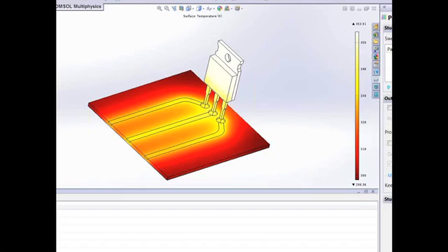Now remember that there were some dimensions that I linked to COMSOL, and the first one was called D1 at sketch 2. So this was a dimension at sketch 2, and there was a COMSOL parameter set up so that it's linked to the dimension. And you've seen that I clicked the plus sign here to add the COMSOL variables.